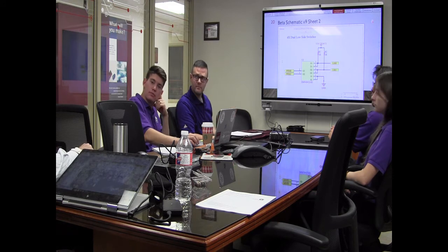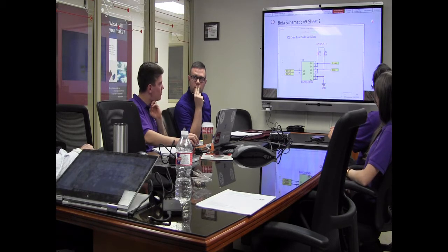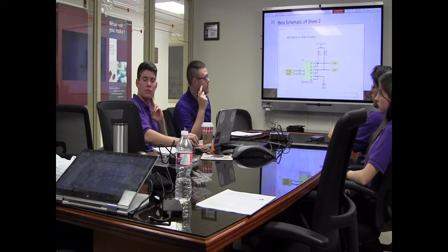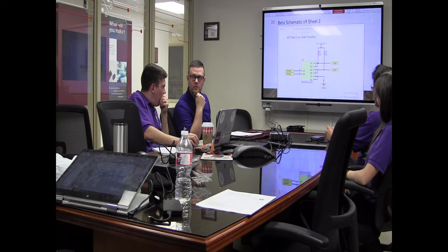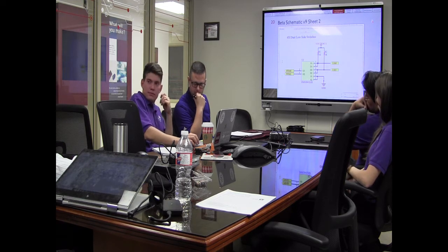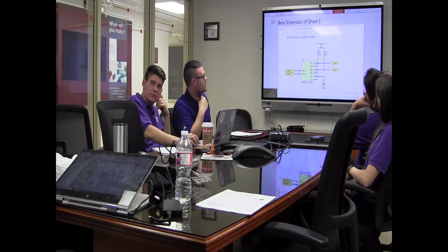So we don't have any of these protected with a back EMF diode, right? We're expecting that to be done off the board. They should be in the next sheet, a little bit closer to the, I believe they are. Well, I think we'll see it in a second. Yeah, I'll be interested to see. There are diodes, but I'm not sure if they're back EMF or not.